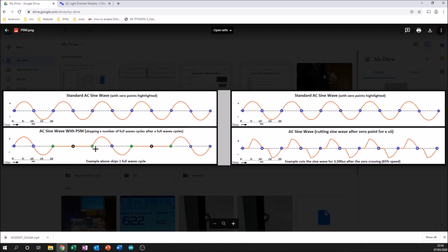That's up to you how you'd set that. The problem with that is you have very poor control. It's not a uniform sine wave. For instance, you could be skipping one full sine wave every 3 sine waves, and it's not symmetrical. You wouldn't be able to run a fan at many speeds, and if you're trying to control something like a light, you'd find it would flicker quite a lot. It's got a lot of harmonic noise as well.